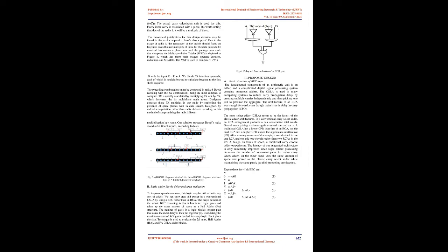CTRLP1 is a control signal that decides whether to select B8_0 or B8_1, as shown in Fig. 6. It will decide the selection as per the control signal, where control equals 1 selects B8_1 and control equals 0 selects B8_0.